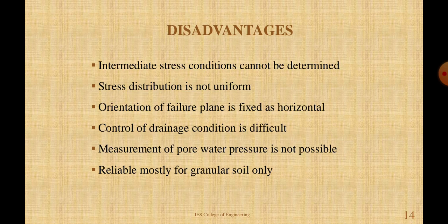Then the disadvantages of direct shear test. Intermediate stress condition cannot be determined. Stress distribution is not uniform. Orientation of failure plane is fixed as horizontal. Control of drainage condition is difficult. Measurement of pore water pressure is not possible. Reliable mostly for granular soil only.